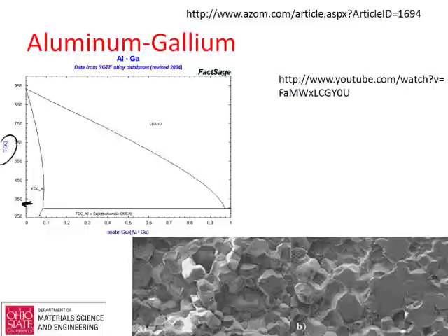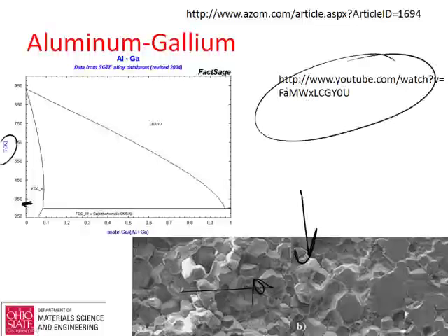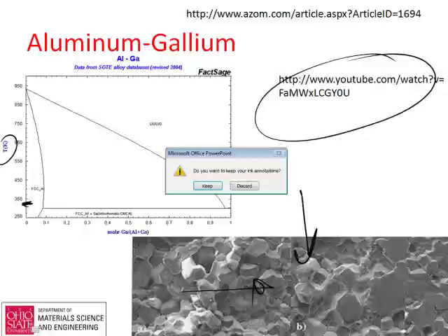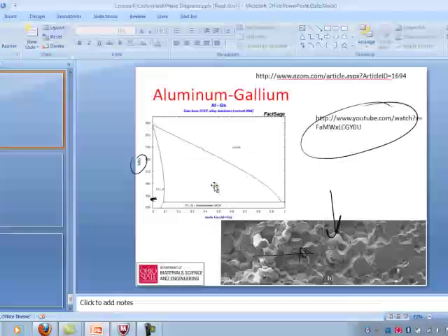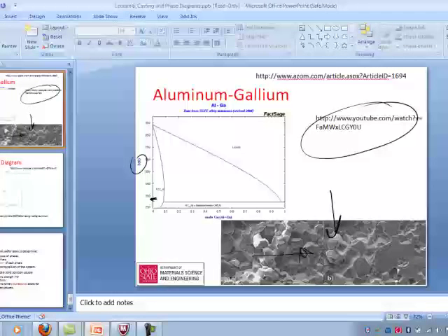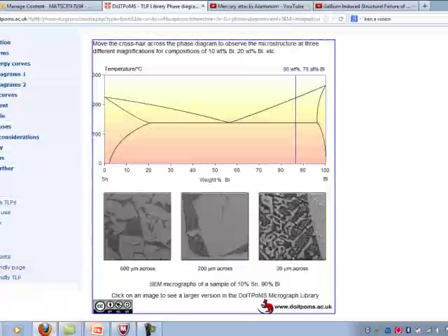And you can do some insidious things with this. And this is what the microstructure looks like. What happens is the gallium diffuses along these intercrystalline boundaries and actually melts the material there if you can get the gallium in there. And there's a nice example on YouTube of what happens. This is an example from the Nerd Rage site that I'll show you in a second here.